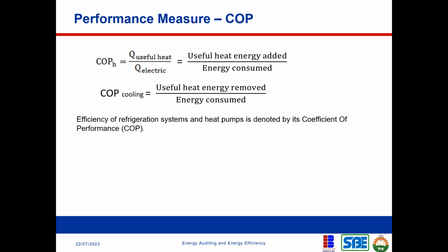So this is just a way to categorize the efficiency of a heat pump. A heat pump is one of the technologies that you can add. For example, you can add 4 units of electricity, 4 units of energy in a heat pump, and you can actually get like 12 units of energy out. So it has a positive impact. You're adding a smaller amount of energy, but you're getting a higher amount compared to what you put in. So we don't want to call it efficiency.